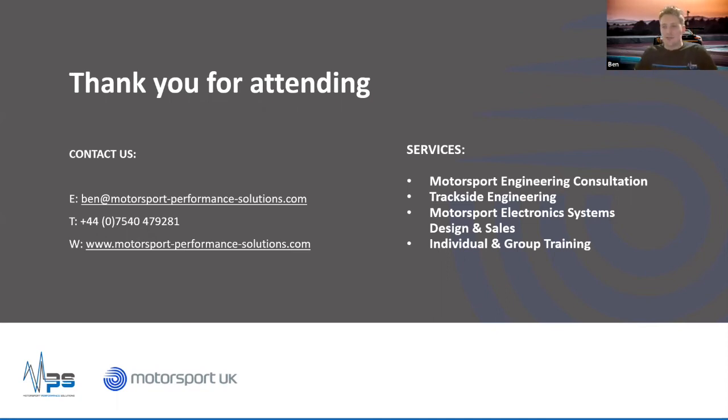The actual value of what the sensor reads isn't massively important in terms of analysing driver performance. Yes, as you do more complex calculations, mounting it accurately and how you determine the C of G becomes a lot more significant. But for the intended audience of this, people that have never used driver data or any sort of data analysis before, you don't have to worry about being that accurate to still be able to productively use the results, if that makes sense.